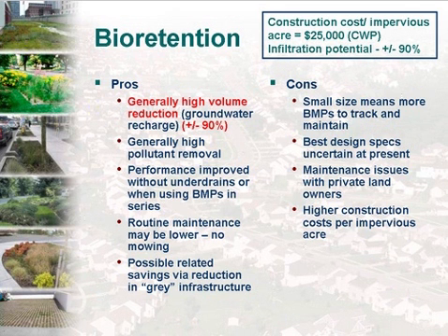Another thing that John mentioned to me is that if you do use that underdrain, maybe it should go to a second BMP to handle those flows. So you can use this treatment train idea to even get better performance. Again, we may have some lower costs here for maintenance, depending on how they're designed, because you're not having to mow all the time. Of course, in any BMP, you're going to have to deal with trash, and in many of these, annual mulching and things like that, and of course, periodic upgrades and such.